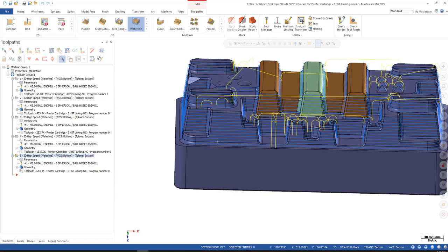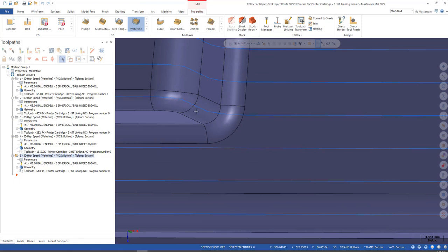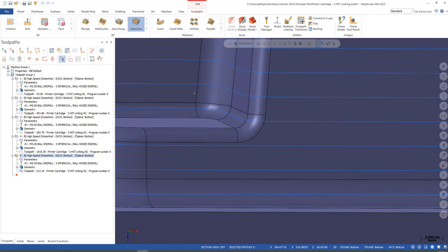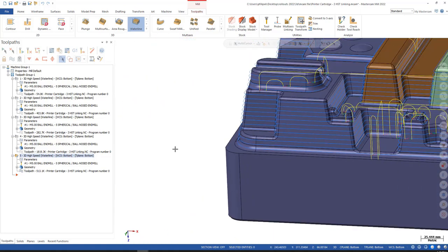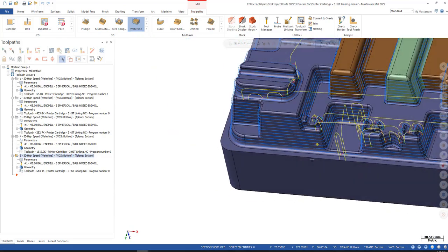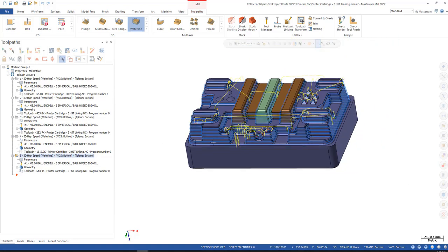Depending on our depth cuts, this is where the problem comes into play. See where that cut is right there? It's above that floor. It's not even near, and then the next depth cut's below it. So you would have a lot of material that you might not clean up on that face there potentially. So that was the downfall. Now they got it fixed. So definitely take a peek at that one.